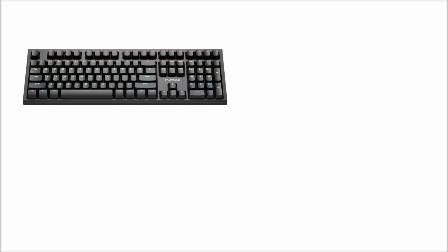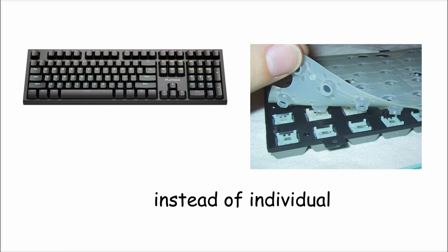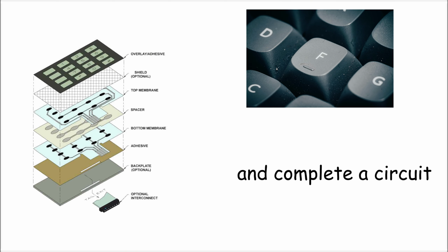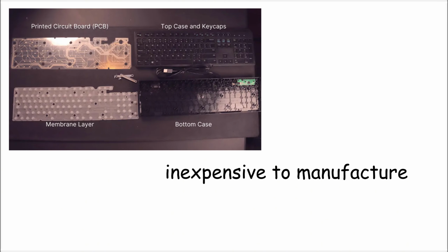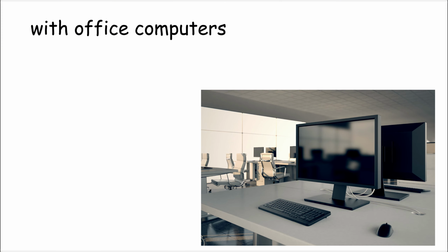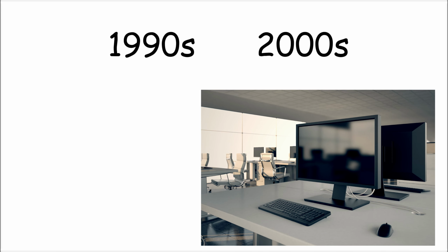Membrane keyboard. A membrane keyboard uses a thin, flexible layer under the keys instead of individual mechanical switches. When a key is pressed, the membrane layers touch and complete a circuit that registers the input. This design is inexpensive to manufacture, which is why membrane keyboards became extremely common with office computers and home PCs during the 1990s and early 2000s.